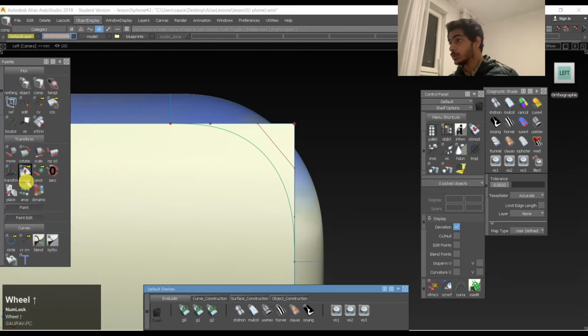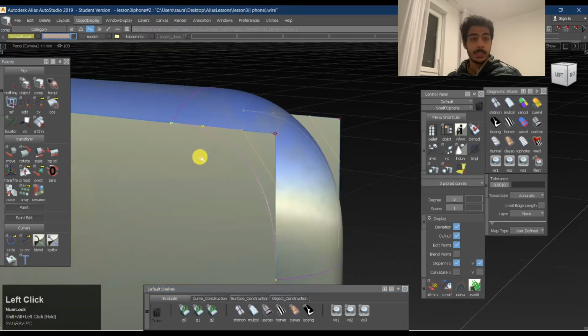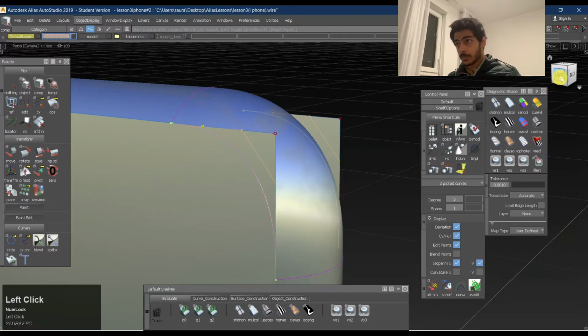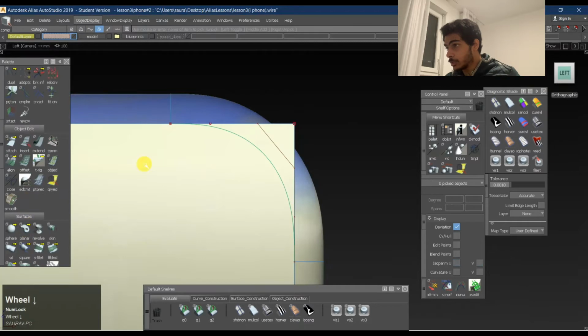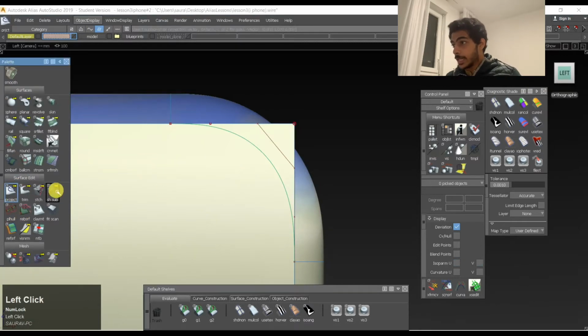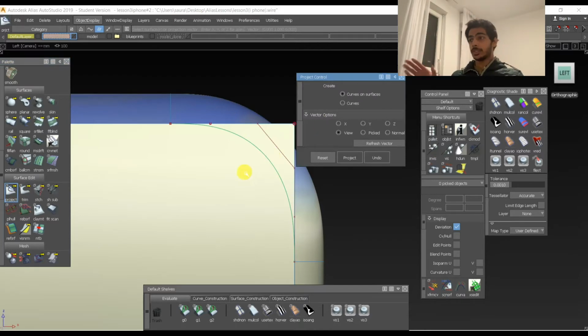So what we'll do is we'll project this curve on this, which makes a curve on surface, which can later be trimmed out to make a single surface or maybe 2 duplicate surface or keep surface or delete surface, whatever you want. So we'll just take a surface over here. It's there in surface edit project, and double click on it. We'll project it by view.